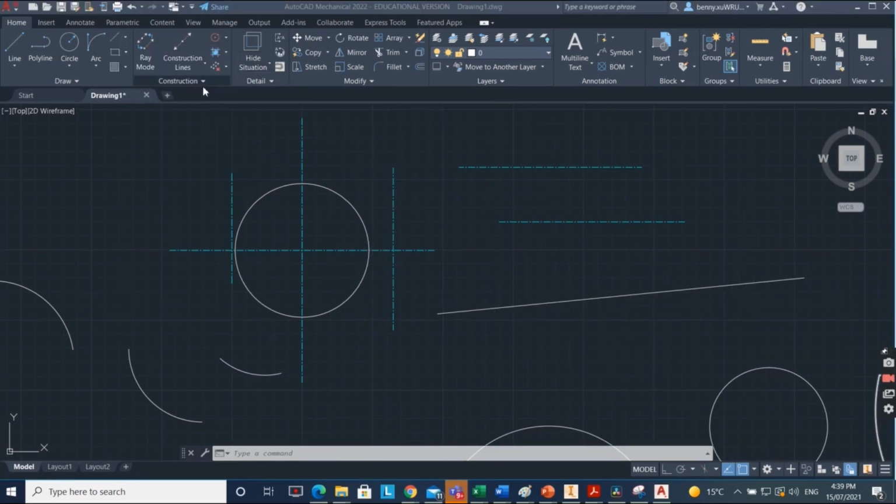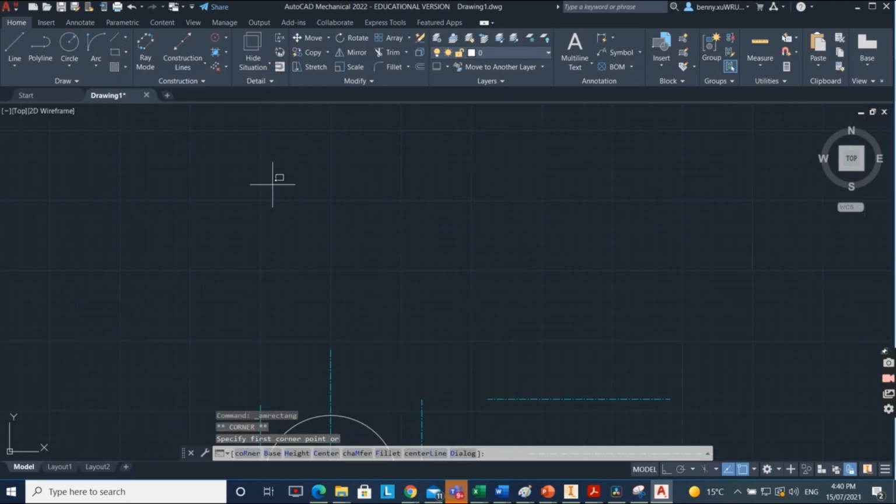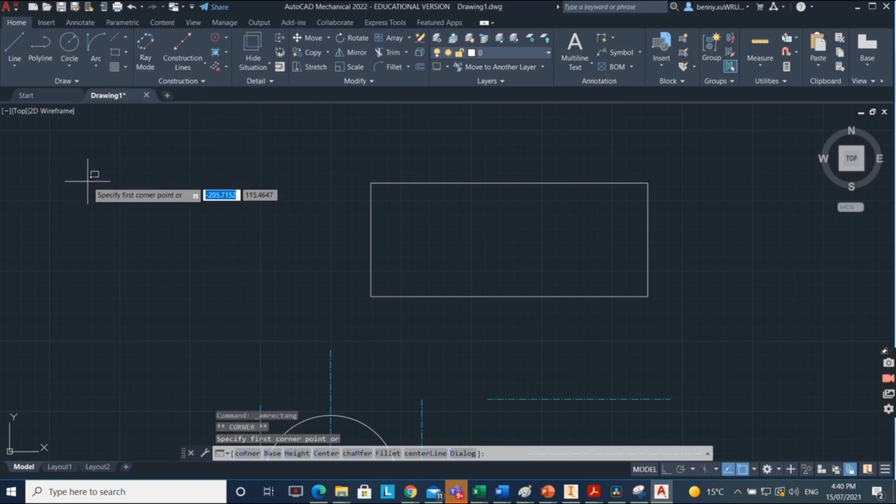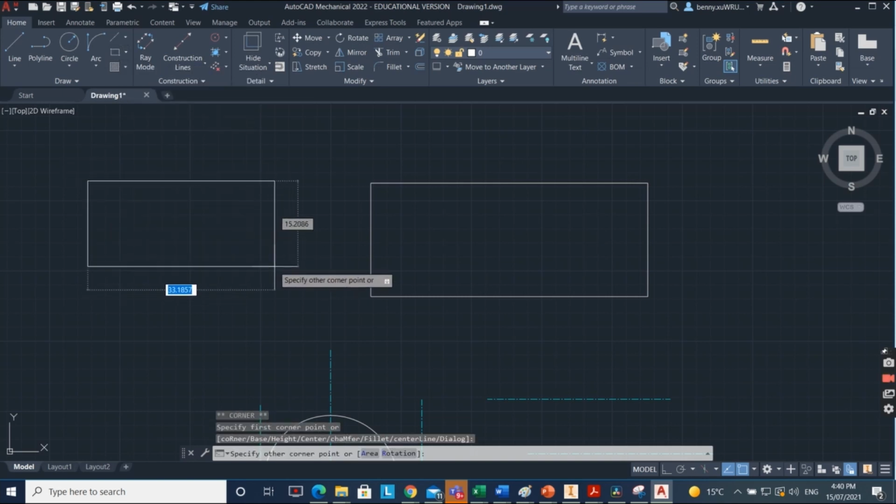Okay, now we move to the next one, rectangle. When I click on the rectangle here, it's corner to corner, not the corner next to it. Select it, allocate a rectangle here. And also, that may be not the rectangle I want. I want to have dimension from here to there and from here to here. Again, this is X and Y. What I want to do is click on there and then type in number.